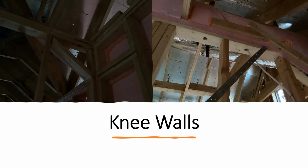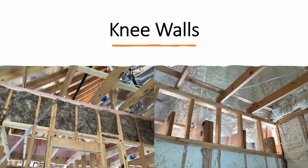It needs to have an air barrier on the back side facing the unconditioned space and air sealed on all sides. The one on the right is a good example of the air barrier and properly air sealed. Both those holes at the top plates should also be poly sealed. Hopefully maybe it's poly sealed on the top inside that cavity. It doesn't look like it, so it should be poly sealed as well.